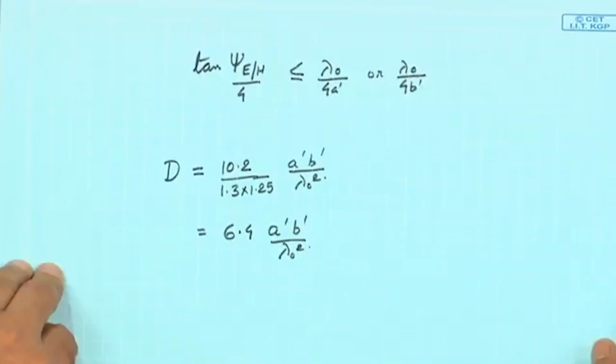In that paraboloidal reflector system, it is called a feed horn. So, as a feed horn also horns are used, and also in large array antennas, for feeds etc., horn is used. Now, since it is so important, particularly for us in laboratories, I will now spend some time on the design of the horn, because that design is very important.